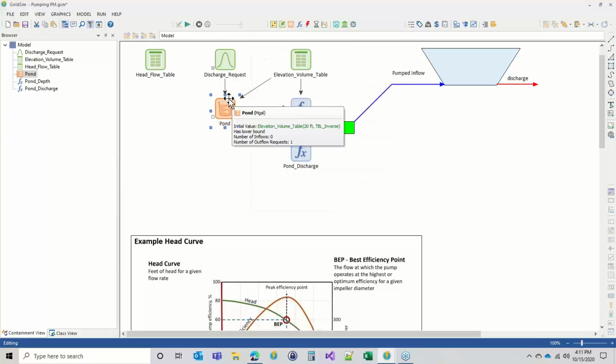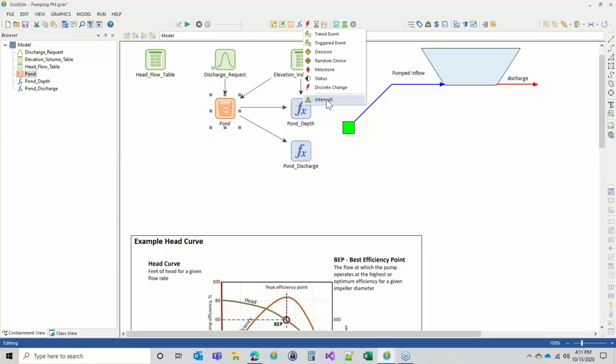And sometimes I'd like to do that with an interrupt, just to notify the user that, hey, this has risen above the upper bound. That is not realistic, and you should change something in your model to prevent that from happening. In our case, we can put controls in how much we are pumping in order to prevent the water level from rising too high. And I think that is a cleaner way to prevent overflow if you need to prevent it.